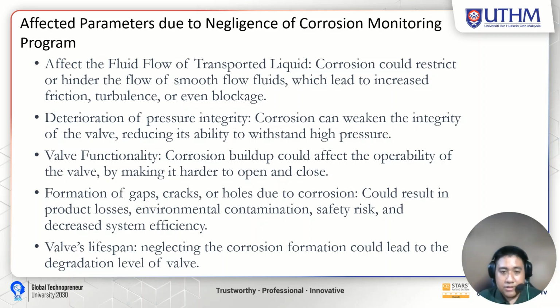Next will be the valve functionality. The corrosion buildup could affect the operability of the valve by making it harder to open and close. Next will be the formation of cracks, gaps, or holes due to corrosion, which could result in product losses, environmental contamination, safety risk, and decreased system efficiency.